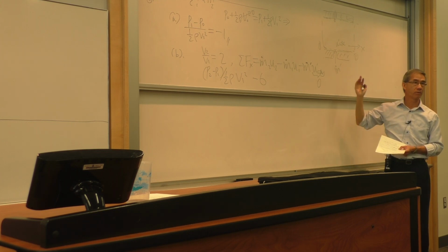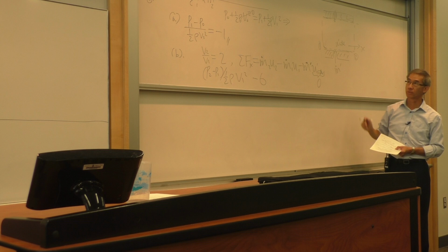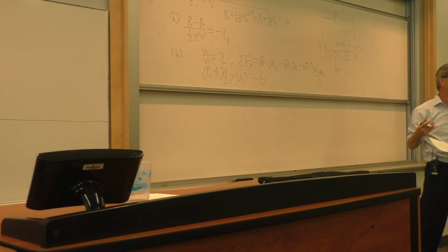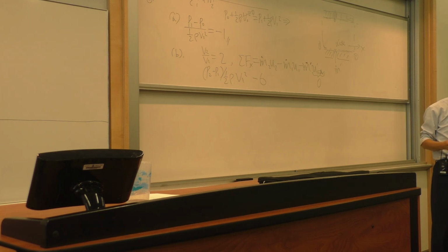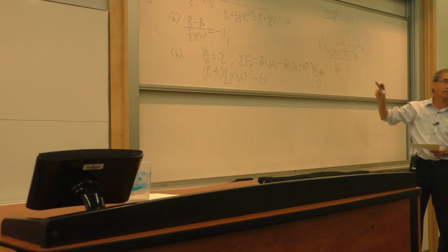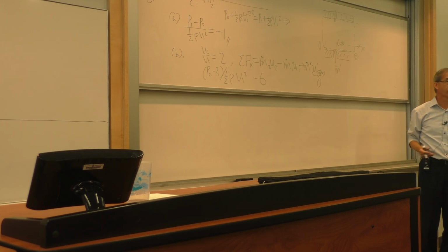So this part B had two implications. First one is, please don't use Bernoulli, the flow is turbulent. A lot of mixing, because you cannot follow a streamline. Number two, in the x direction, if there's no momentum in the x direction, then the momentum flux is zero. I have no contribution to the forces. Do you get it?